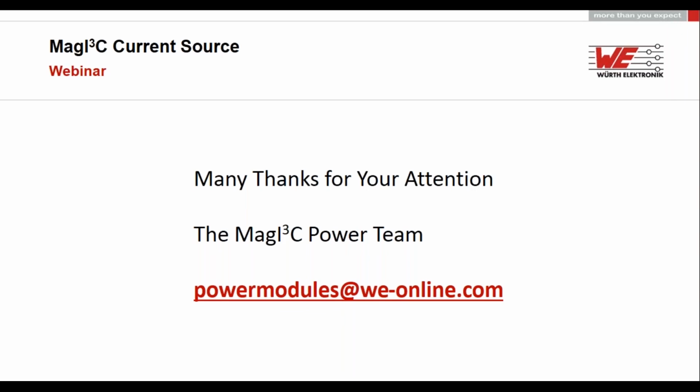Yeah, basically you can use any power module. This is an order code, which is a quite new module, but this behavior is exactly the same as other power modules we have. You can directly use these power modules to charge any accumulator or battery which is available. One thing to consider is to look at the specifications of the batteries, which maximum current, or if you want to have a trigger charge, for example, or some special waveforms for charging. Everything is possible with this reference design, or in general with a power module controlled by an external error amplifier.